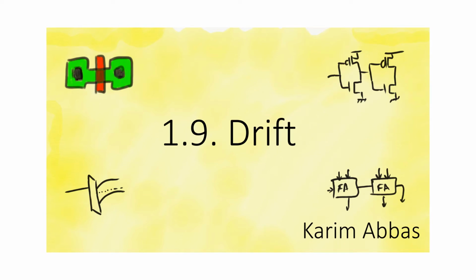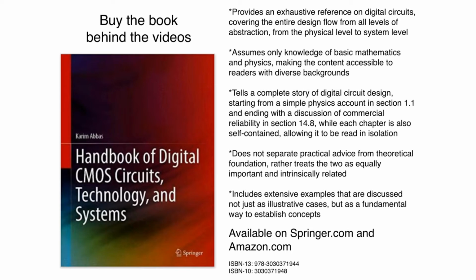So we will start by discussing the first mechanism of charge transport, which is drift. If you consider an electron or a hole, it's a particle in space, and this particle, if it is free, is going to move. The first kind of motion we can imagine for holes and electrons is something called thermal velocity or thermal speed. There is an amount of thermal energy in the system equal to 3/2 kT. This is going to be translated into kinetic energy for electrons and holes.